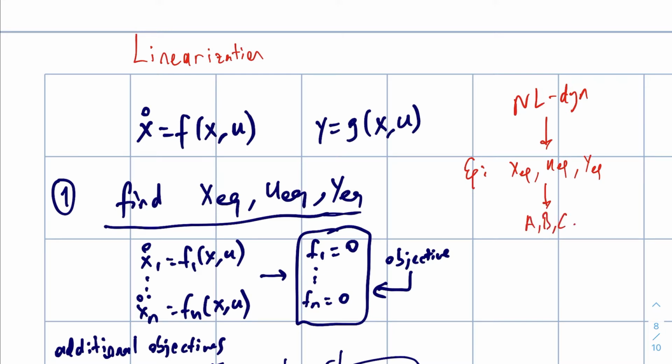So we will have A, B, C, and D matrices. And by using those matrices, we will construct a linear plant, a linear LTI dynamical system. By using this plant, we will design a K controller. It can be a reference tracking application or just for regulation purposes. And then you will test this controller, this K object, on the given nonlinear dynamical system. You might like to do that in Simulink probably.